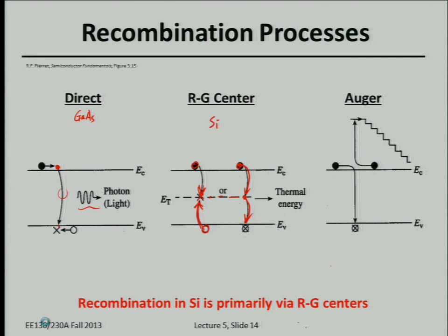So basically, once the electron tends to go back from the conduction band to the valence band, the second electron, the third particle, start to absorb all the energy within this process. And these 3 electrons go to a very high energy level, very deep into the conduction band. In the following process, as you can see the step curves here, the second electron takes quite a long process to gradually release the energy and go back to the bottom of EC. So basically it's called the Auger recombination process.